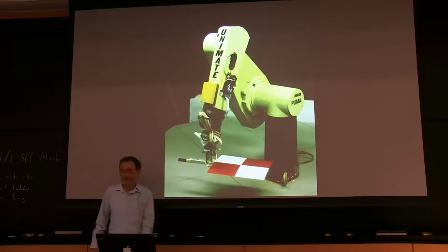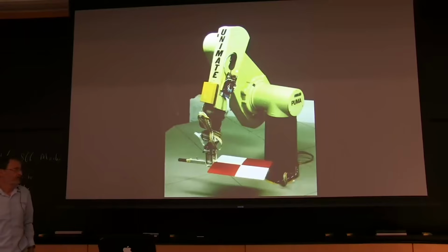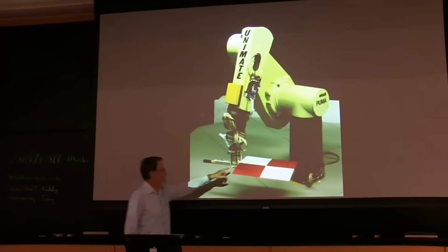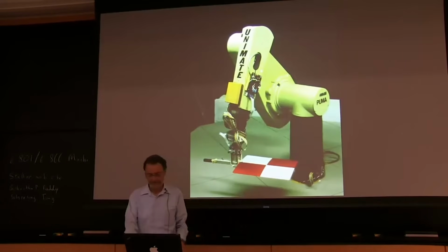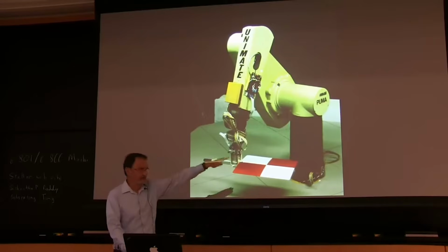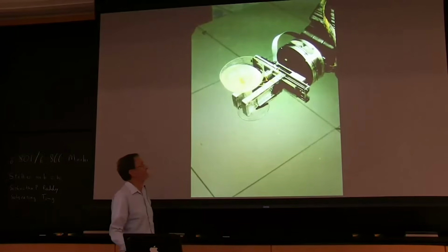This is something called a Surveyors Mark, because surveyors have used that trick for a very long time. It's easy to process the image, and you can find the location of the intersection of these two lines very accurately with sub-pixel accuracy. So you move that around in the workspace and then find the, fit a transformation to it, and then you can use that to,